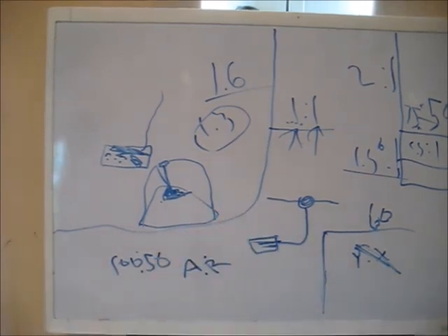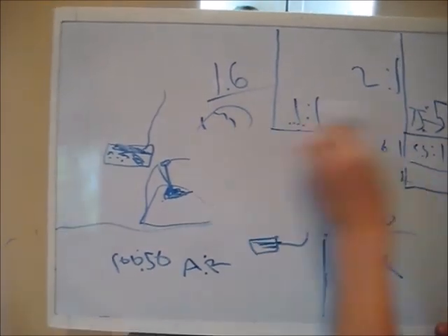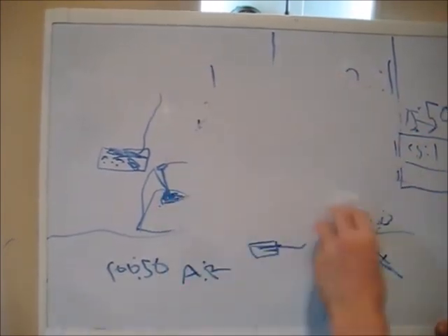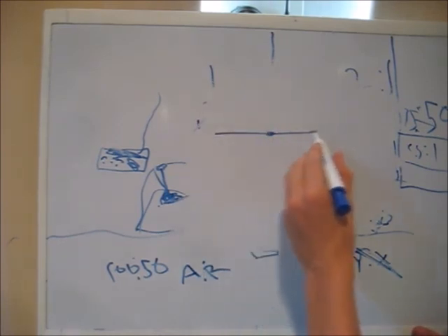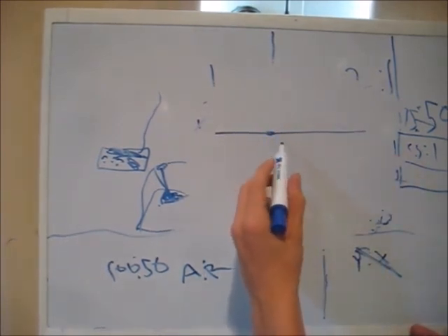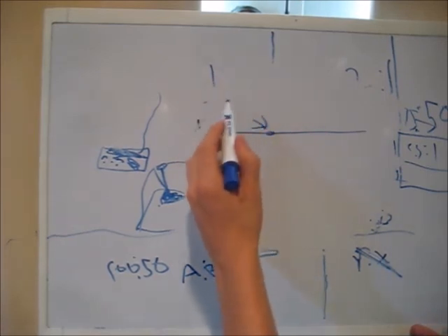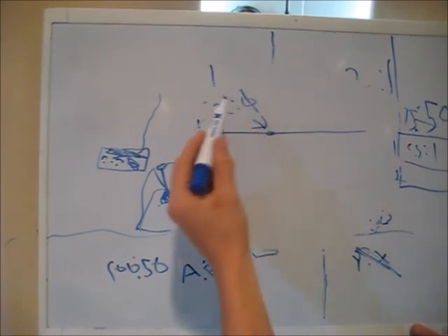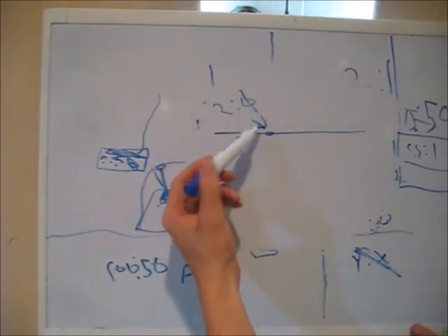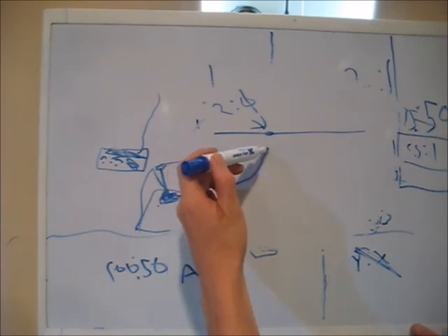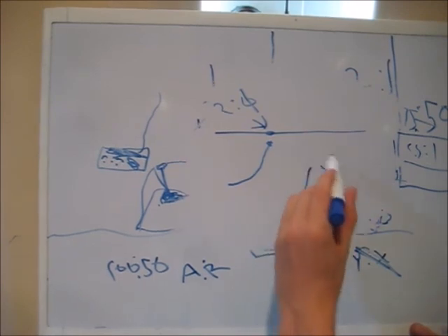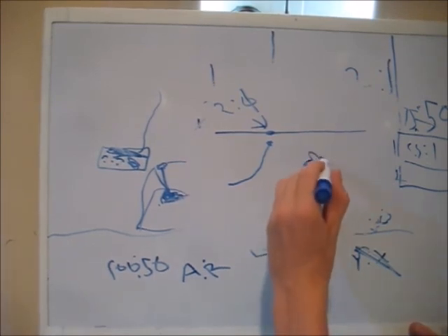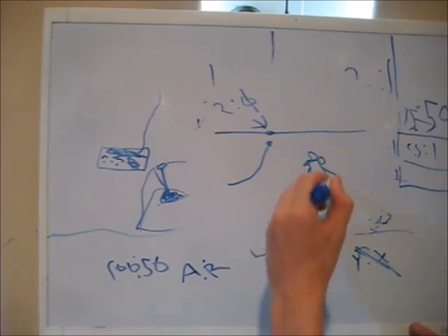So there are a couple ways to fix this, and the first easiest one is tuning your antenna. But if you don't want to tune your antenna, or if other factors come into play, they make something that can help you with this. If you put some wire in the air, and right here, the SWR is 2-to-1, meaning that this is 100 ohms, and you have 50 ohm coax coming up, well, that's not going to work. You're going to have some SWR problems. They sell a balun. A balun is a feed point type of thing, and this is just a crude drawing of one. They come in a lot of different ways.